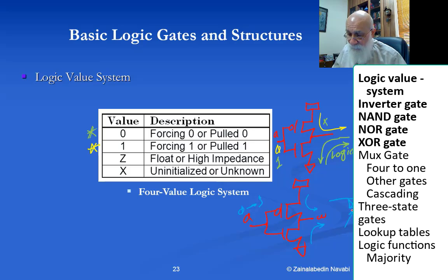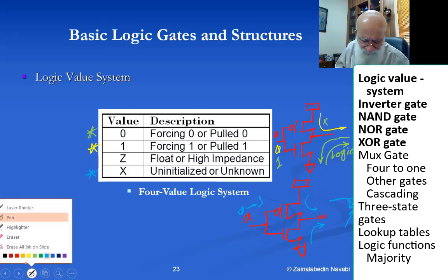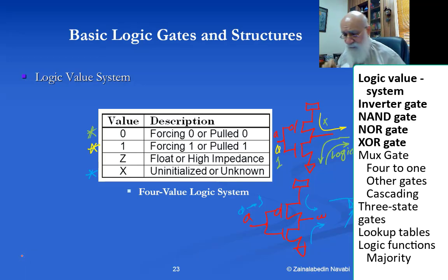So this value here is neither a 0 nor a 1, it's a conflict. And therefore, how do we represent that? Well, I represent that by X, or the conflict here. The opposite of it is also true, and in that situation, let's use still a different color, and I'm going to use orange, and let's say my A is 1. And the A is 1, this is conducting, putting a 0 on the output, and therefore my output is 0. And later on it changes to 0.